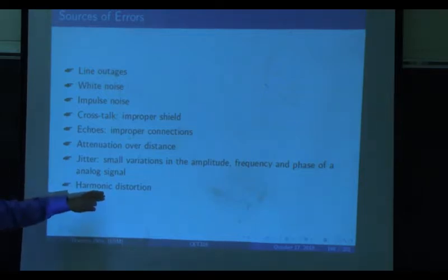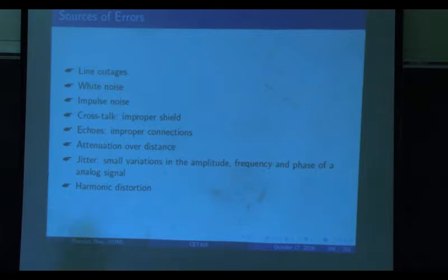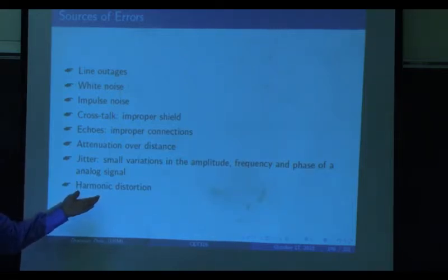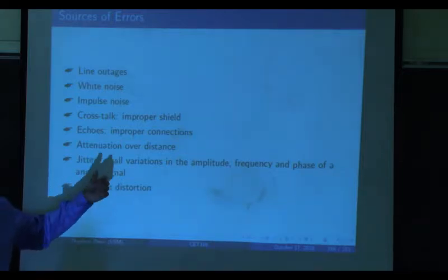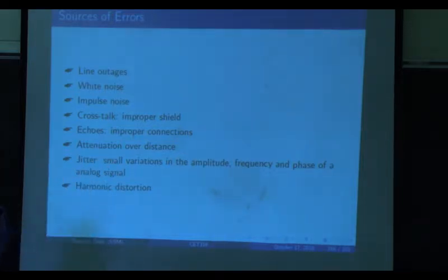Harmonic distortion. Harmonic distortion means you have a nonlinear device inside your system. We need to have a nonlinear device, right? What device is nonlinear? Resistor? Is a resistor linear or nonlinear? Linear, right? Capacitor is linear. Inductor is linear. What is nonlinear? We mentioned this when we did the transformers, nonlinear versus linear devices.